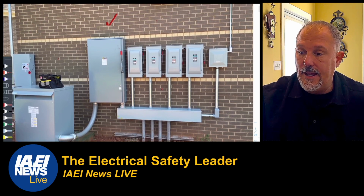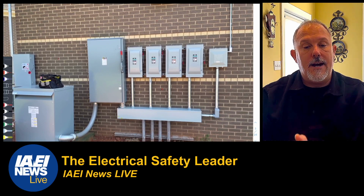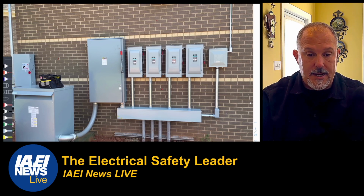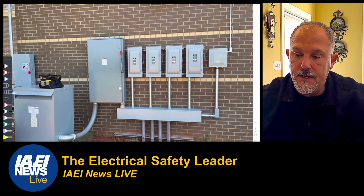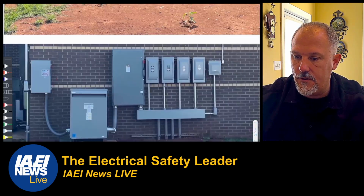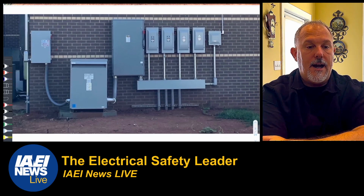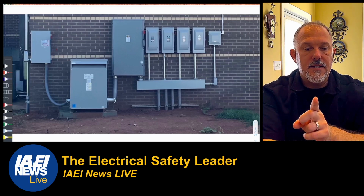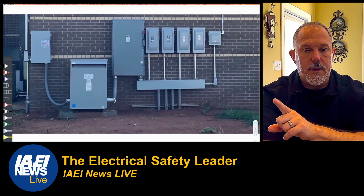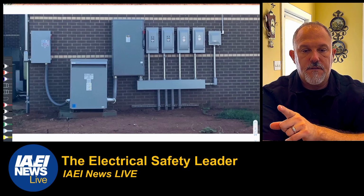It says, where the conductors are located outside of a building or structure, except at the point of load termination, and comply with all of the following conditions. So far, this application is definitely outside, right? So we can definitely say that we're meeting 4 so far. But it has to comply with all of the following. 1, the conductors are protected from physical damage.